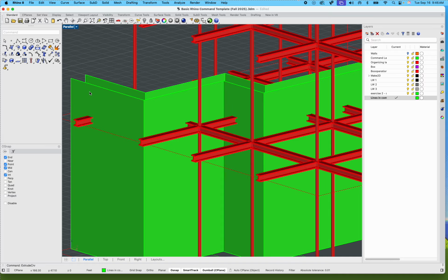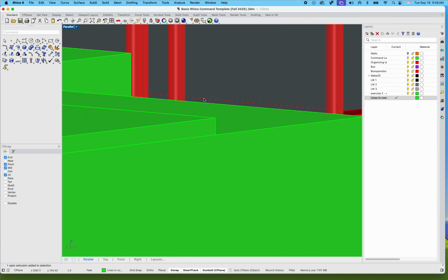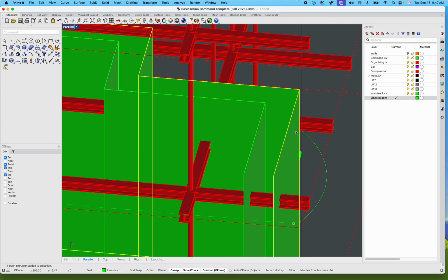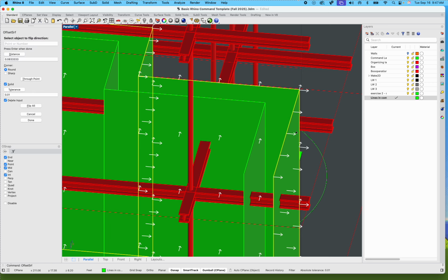I like it, but it's still actually flat, right? I mean like mathematically flat. It literally has no thickness. The only reason it's showing us thickness is because it's a computer, right? But if I was to 3D print this, nothing would come out, right? Because it's not actually thick. It has no dimension. In our case, let's add some dimension to it. So I can offset surface, not just lines, but now I can offset surfaces as well. So I'm going to take that surface.